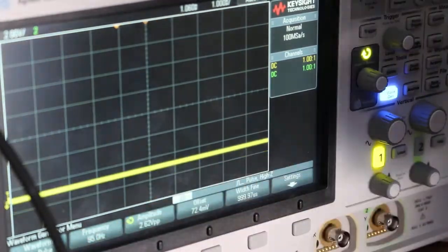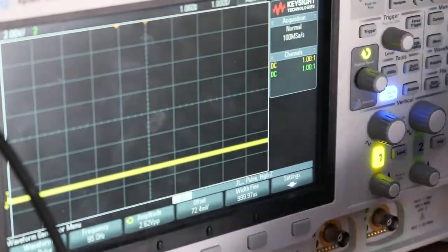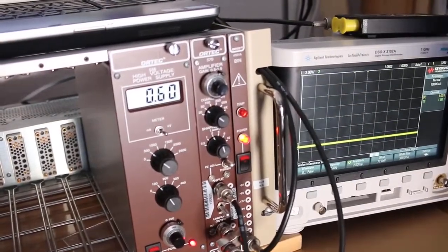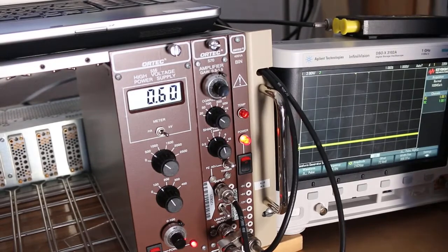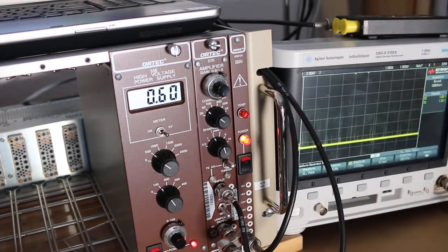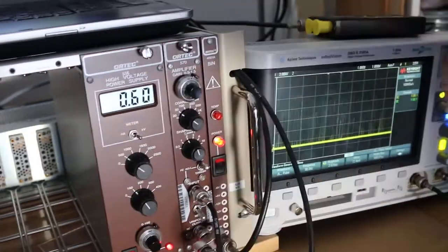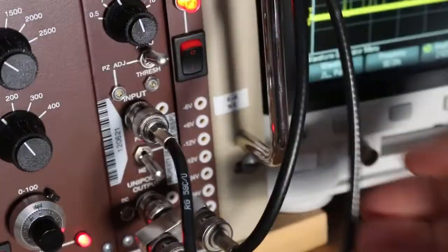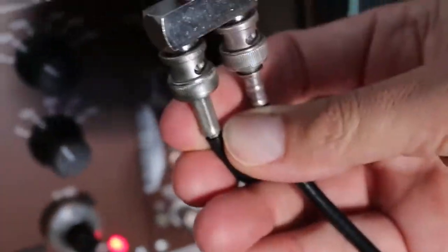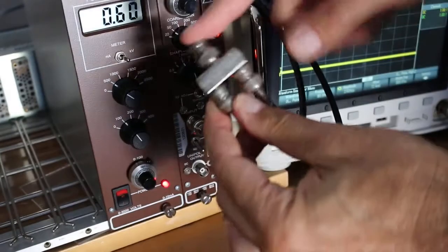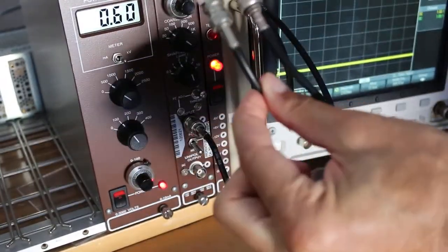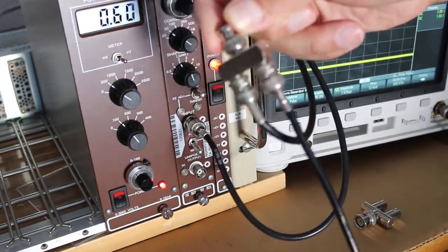So let me take this cable off. We don't need it for the moment. Now I'm going to go back over here to the amplifier. Let me connect the gamma ray back. Remember, this is the key gamma ray signal coming in. The trigger level is all messed up, so we don't see the core gamma ray source, but I'm just going to pull this whole connector right off the output of the amplifier. Remember, this is a signal cable that's split two ways. It comes out of the amplifier right here, and this cable goes to the oscilloscope and this one goes to the data acquisition box, just a T in there that's splitting the signal.